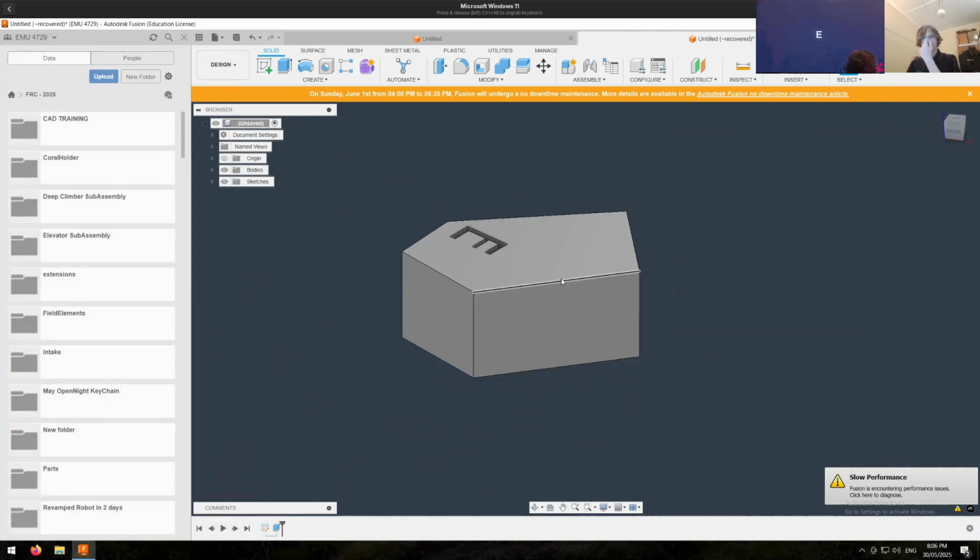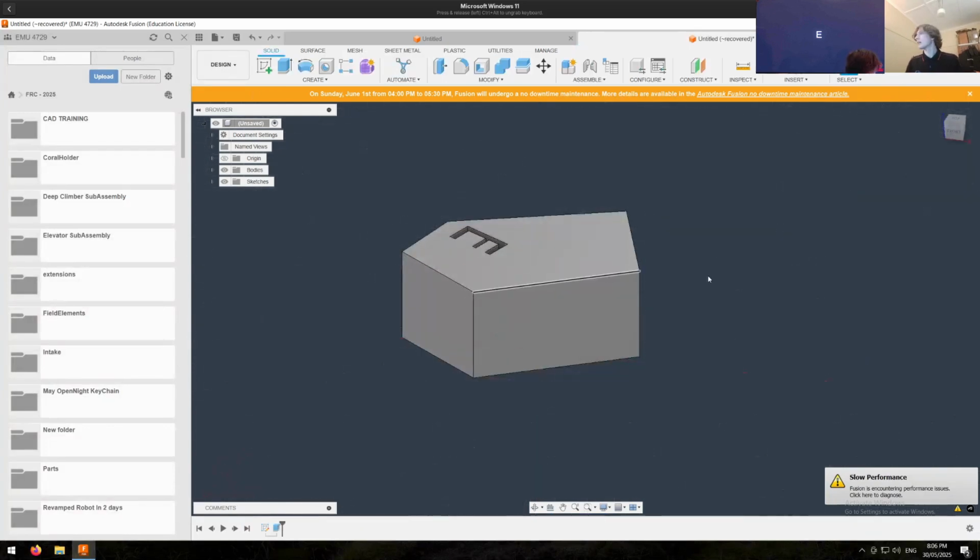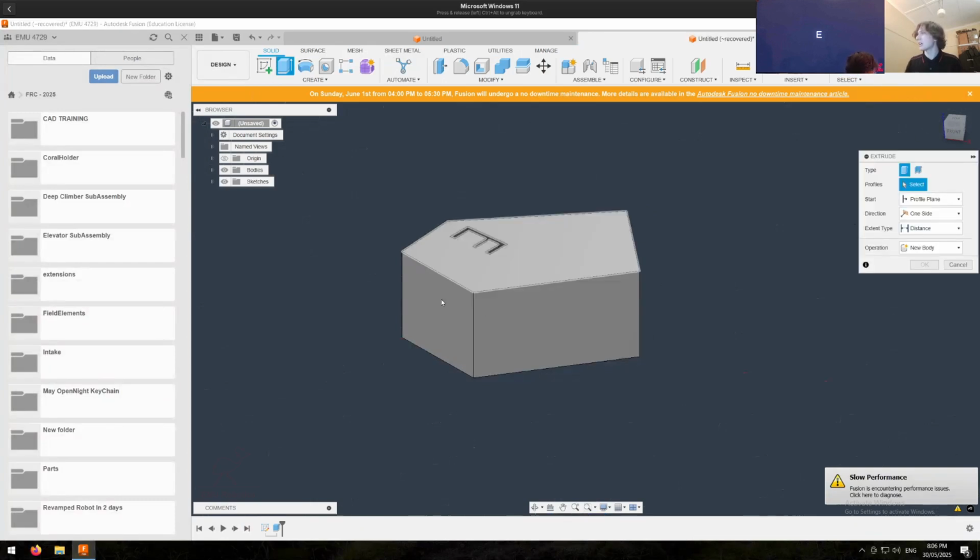That's pretty cool. Let's say I want to make another shape from my sketch. So I'm going to press Control Z for a second just to go back to my sketch. Let's say I want to make this little half donut. So I'm going to press Control Y to redo. Where's my sketch gone? I can press E to extrude, and I've still got that menu up, but there's nothing I can click on. So what Fusion sneakily does is, I'm not sure if you've noticed this browser menu up here. You can see how there's sketches, bodies, and then other stuff that we don't care about.